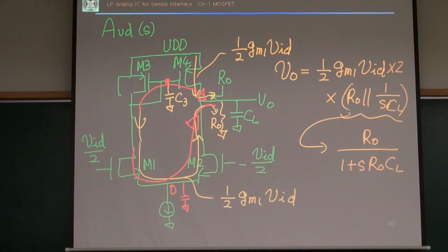So, the small signal resistance looking here is 1 over GM3. That's the resistance there. So I have a pole for the upper path. This is signal path 1, signal path 2. For signal path 2, I have a pole generated by 1 over GM3 and this C3.